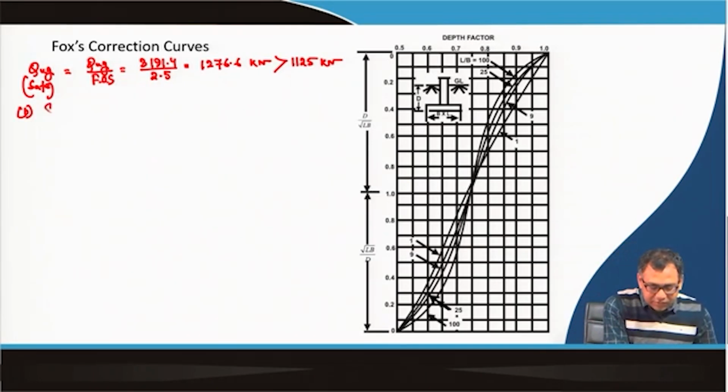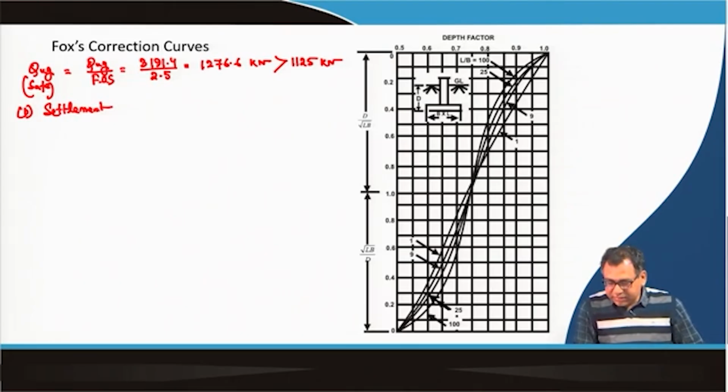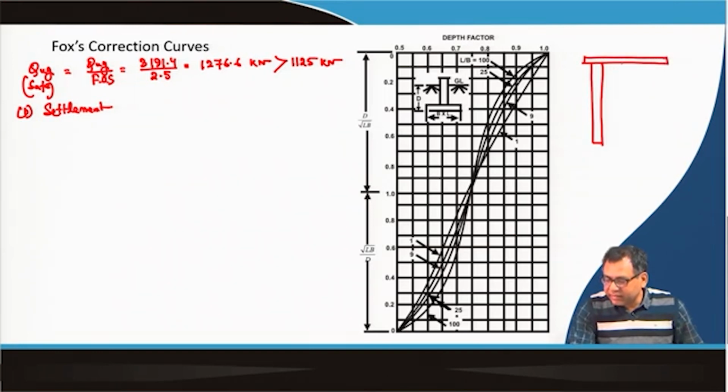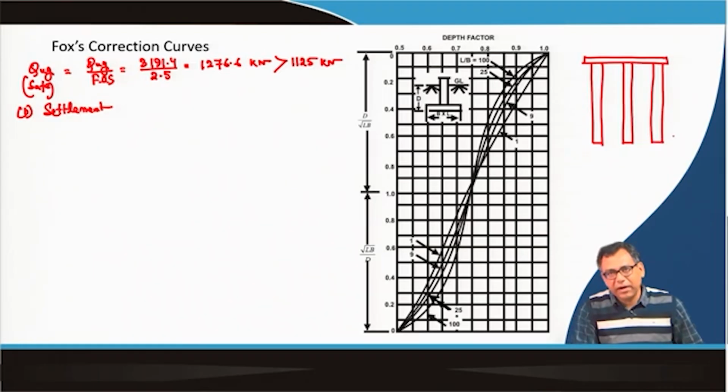Okay. So, for the settlement consideration, so this is the pile group, and we have mentioned here in the question that the soil is in greater depth, the extension of the soil layer. So, that means here we consider it is a homogeneous soil. So, we will put it at the 2/3 from the base of the, or from the top of the pile.